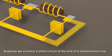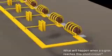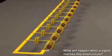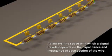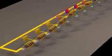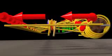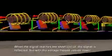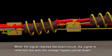Suppose we connect a short circuit at the end of a transmission line. What will happen when this signal reaches this short circuit? As always, the speed with which a signal travels depends on the capacitance and inductance of each section of the wire. When the signal reaches the short circuit, the signal is reflected, but with the voltage flipped upside down.